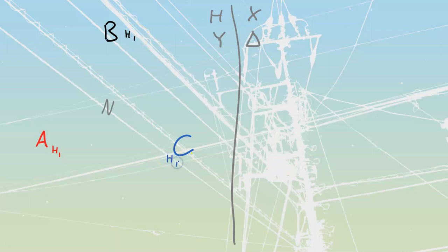H1 and H1. The other thing that we are going to talk about is the fact that H1, I'm just going to draw it here in gray down below, and H2 had, at the very beginning of the module, specific things that they were. As far as my phasors were concerned, H1 was going to be the tail. This is a drawing convention, and H2 was going to be the head. So on all of mine now, I'm going to start dropping in the arrowheads. They were not important when we were going Y-Y or delta-delta, but now that we're going to be mixing, it's super critical that you maintain those little arrowheads. You'll understand why in a minute.